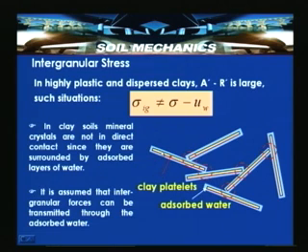So, here in this slide, we have clay particles which are represented as platelet particles and surrounded by the double layer water, electrical double layer water, the adsorbed layer, and then this water surrounding the soil particles. So, the clay particles and adsorbed water are shown here. Depending upon the deposition and the concentration of the salts, this type of arrangement can be there, like face to edge and edge to face orientation.